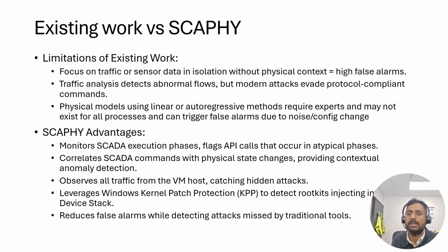Because they're able to correlate physical states with network traffic, they're able to better recognize and have a better context with all SCADA commands. And they're also able to observe all the traffic from the VM host so they can catch hidden attacks. And they're using Windows kernel patch protection to detect rootkits that could be injected into the VM. And overall, they're able to reduce false positives that may be missed by traditional tools.